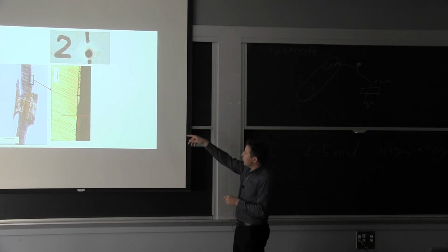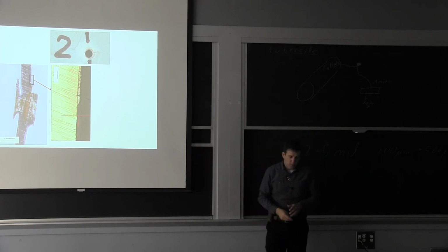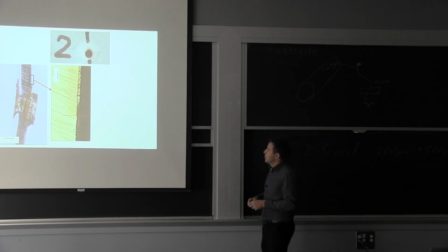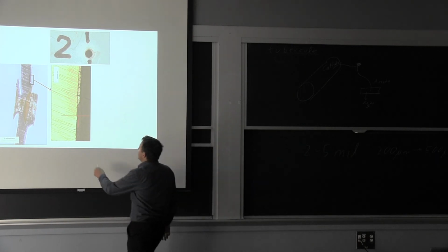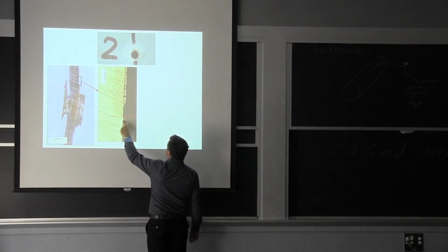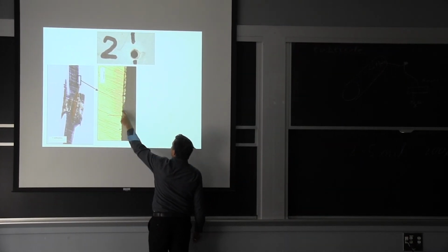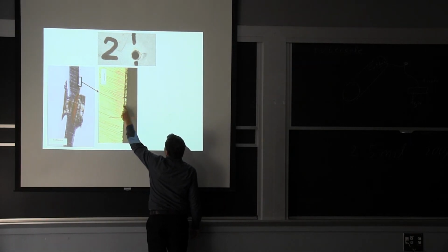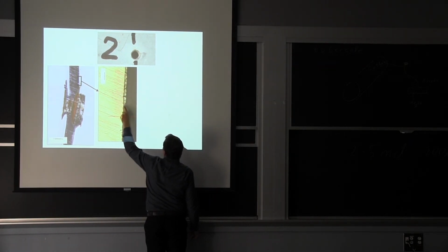So here we have a hole in the galvanizing. This is the perfect situation where we want to use our sacrificial power to protect those surfaces that are exposed. But what you can see over here, the hole is approximately here. We couldn't show it all on that image. From the hole on the surface, you can lose the galvanizing up to about 1/8 to 1/4 inch, depending on the condition.